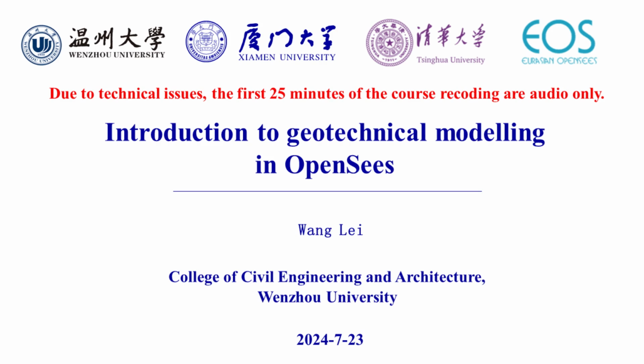This is the core SSI system. You can see a lot of numbers in this figure, right? The number within the circle indicates the tag of the beam column elements. The number within the rectangle indicates the tag of the soil elements. And the number in plain text indicates the tag of the nodes. The SSI system can be divided into 3 parts: the frame structure, the soil, and the interaction between the soil and the frame structure.